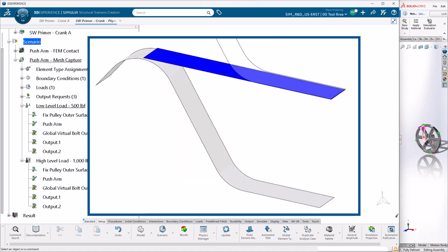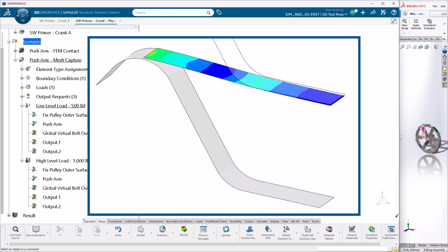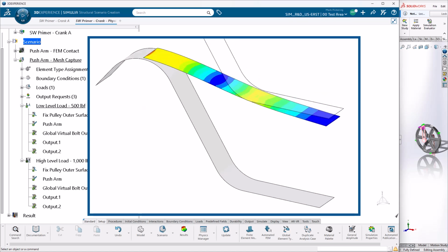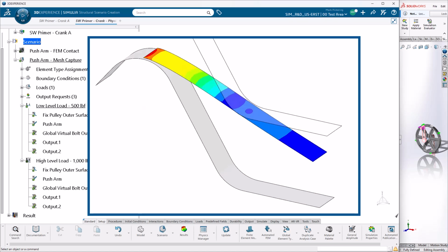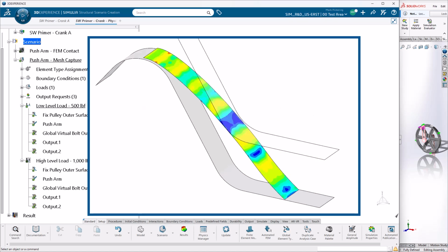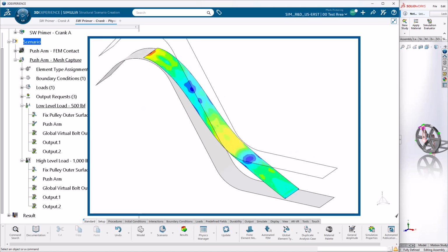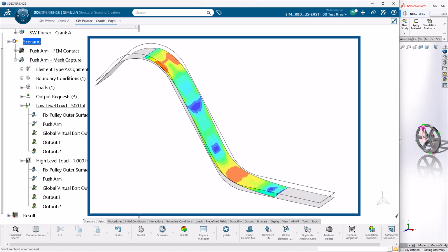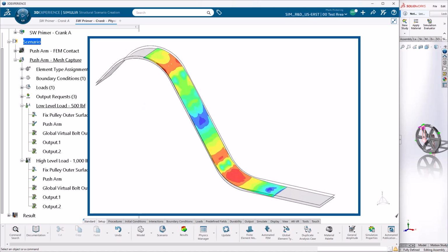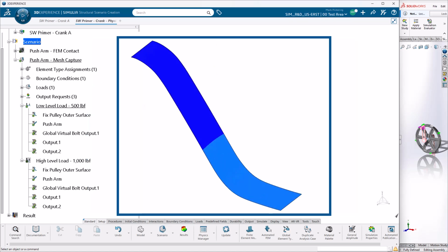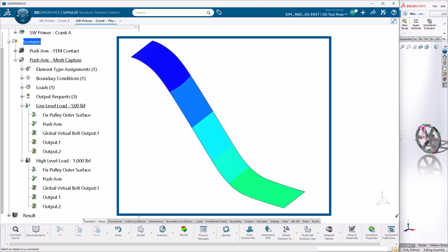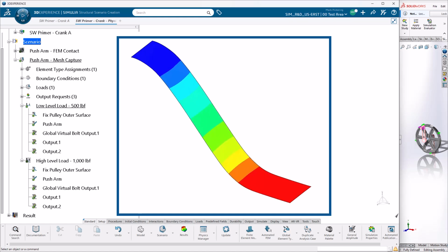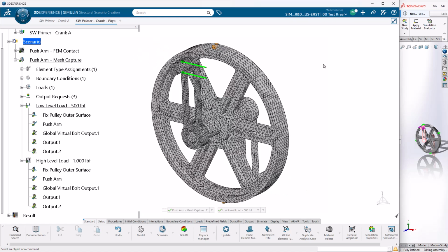In this example, we see why the more flexible approach of multiple FEMs, multiple analysis cases, multiple steps, and even multiple solvers helps analyze more varied problems. This does, however, mean that there are additional choices that you as a user need to make in order to determine how to set up any particular analysis. This is extra levels to consider than the more structured approach that SOLIDWORKS studies provide, but this more free-form combination of different concepts is what provides the flexibility to analyze different problems.